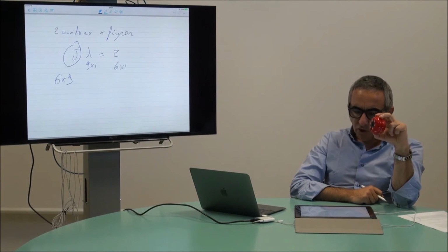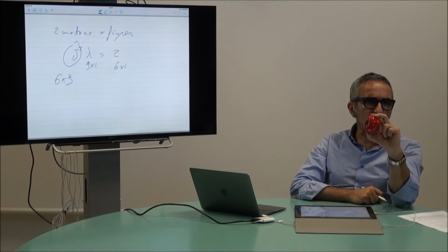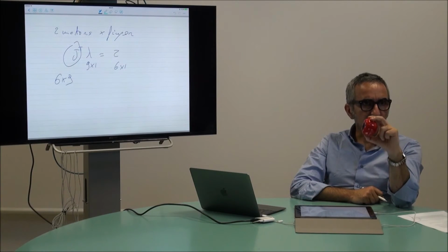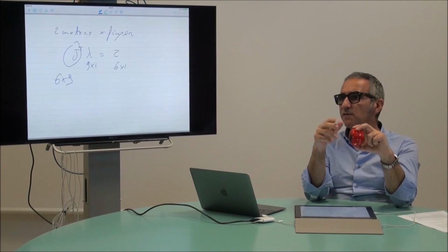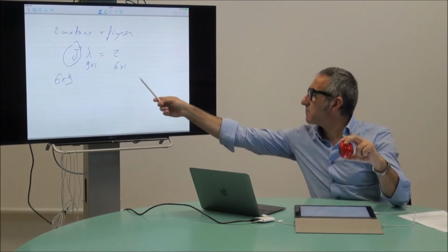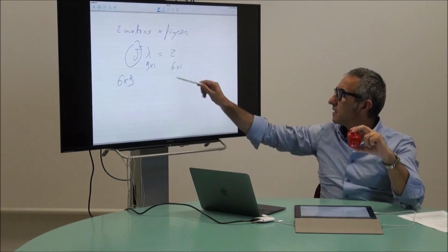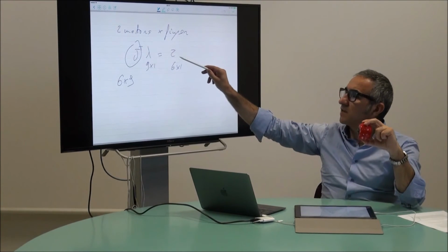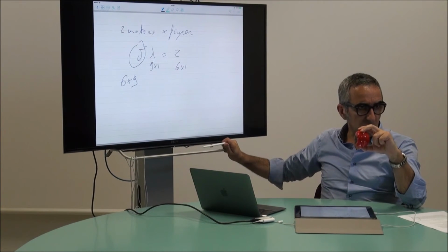Okay, which means that for any lambda, it is not true at all that you can apply a torque to generate that lambda, because you have more equations than variables. Your variables are tau, the torques at the joints that you can apply. If someone gives you lambda that is a 9 by 1 vector, okay, gives you 9 parameters, you have only 6 parameters to satisfy those. It's not possible at all.